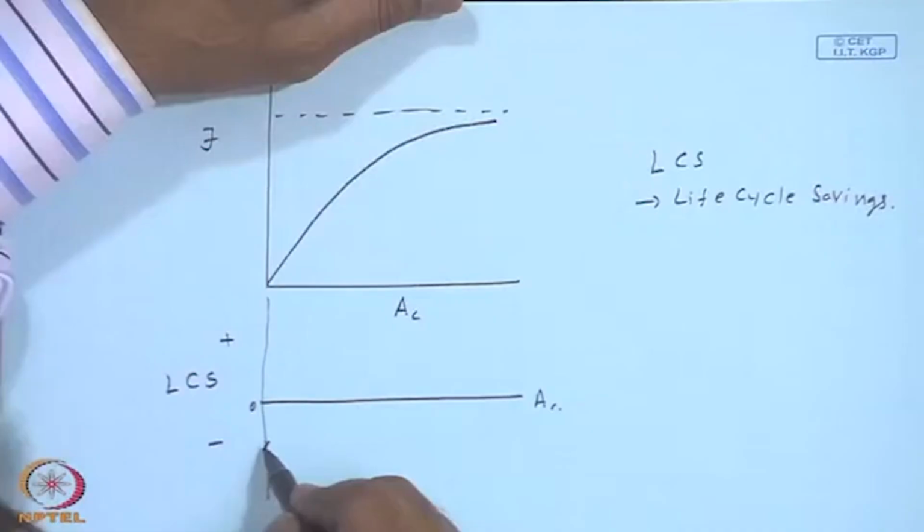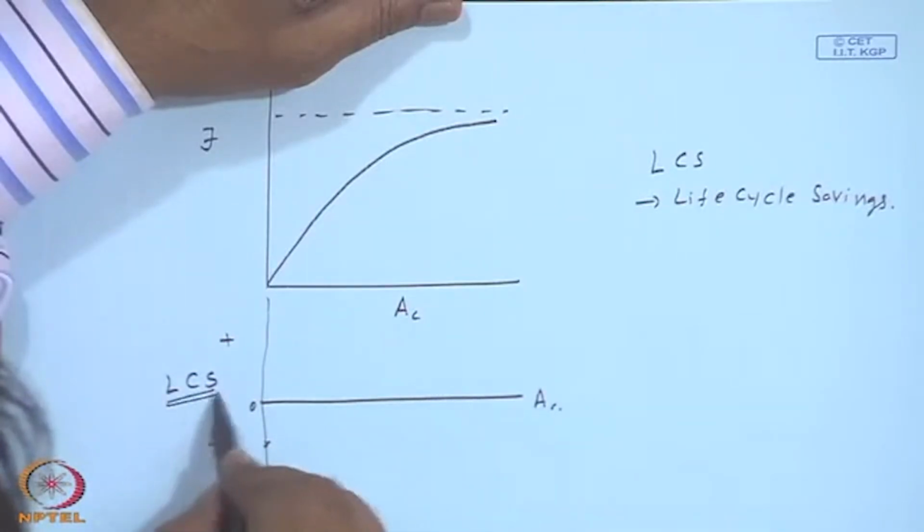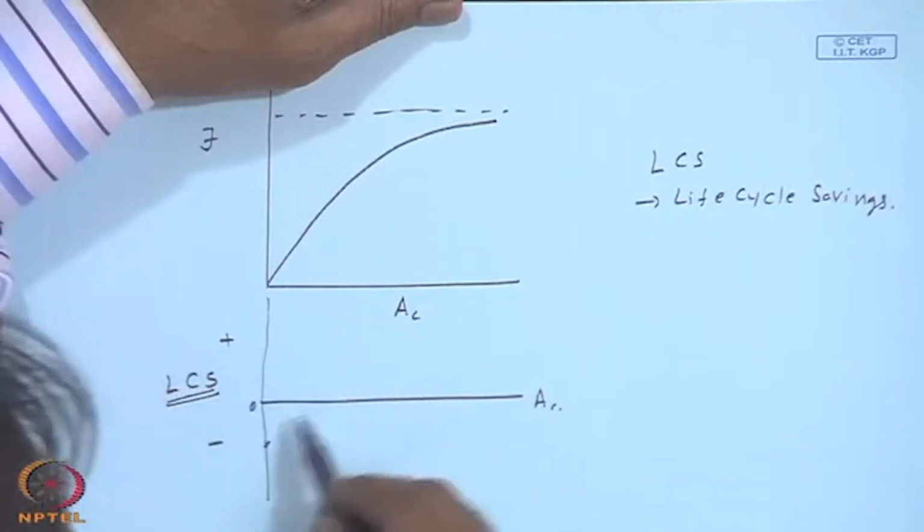One can take, depending upon the reality of the situation, the inflation in the oil price or the conventional fuel price, and the depreciation of the system, and the interest that you pay for the amount invested in initially installing the system. So, this is a complete economic exercise which will ultimately give you, if the collector system is going to operate for a period of 10 years, a net profit or net savings of so much. So, when the area is 0, but you have spent money on the other components, you will not have any life cycle savings, only a negative life cycle savings.